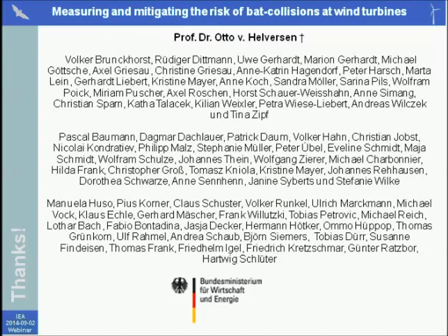So during the first half of the day, the second half of that night, wind speed was rather low and below the cut-in wind speed defined by our algorithms, so the turbine was not running. During the day it would run normally, and then in the evening the wind speed was higher, and except for one time slot at around 9 p.m. the turbine would be running normally. And the black dots are recordings of acoustic bat activity. In this sample, the acoustic activity was within the times where the rotor was stopped to avoid collisions with the turbine.